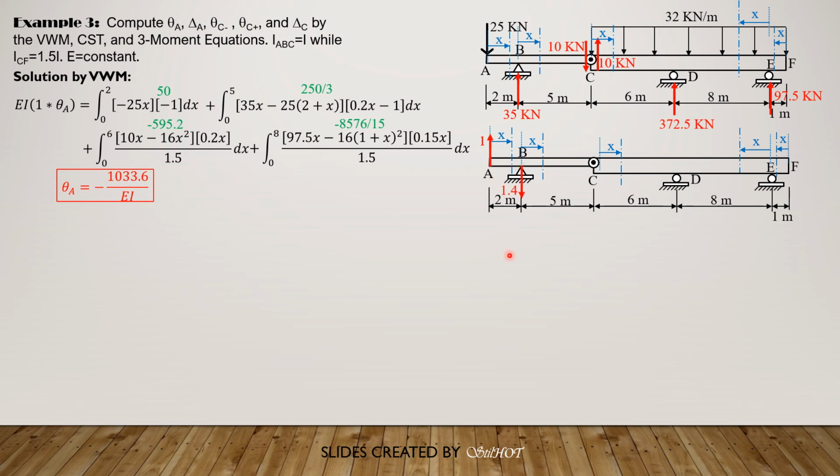So 1.4 downward here. Then summation of vertical forces, it should be 0.4 upward just to the left of C. Then by action-reaction, 0.4 downward just to the right of C. Then summation of moment about D equals 0. This is counterclockwise, so the reaction at E due to this force should be downward. Then reaction at E times 8 equals 0.4 times 6. So the reaction at E should be 0.3 downward. Then the sectioning is already there.